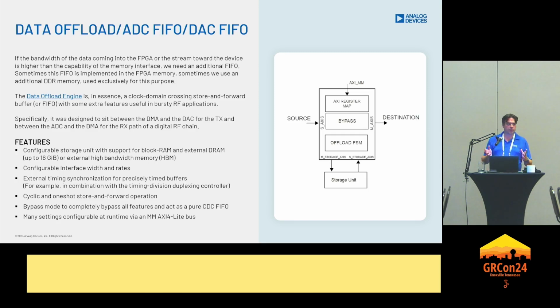On some of the FPGA carriers, there's dedicated DDR memory that is not really the system memory for your processing system. You can implement a DDR controller in the fabric and then use this DDR memory that is not used by anyone else, and you can stream into it at really high throughput, almost the full theoretical memory bandwidth the DDR has on the datasheet.